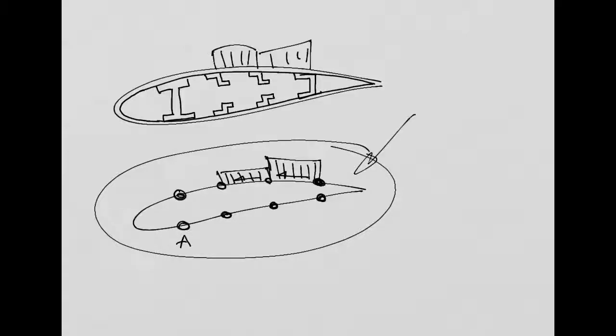So if you don't have a simplified model, at least for the initial iterations of your design, that can give you an idea of how these shear flows and bending stresses are distributed on the cross-section, then you will waste a lot of time in these initial iterations of your design, right? Which is really a waste of time and money. So this structural idealization is really very convenient for designers to have an idea of how these stresses distribute on the cross-section, and we are going to start doing this analysis next week, okay? So we are going to spend much more time on these idealized cross-sections than the time we spent on the fully effective cross-sections, because that's what we use more in practice.